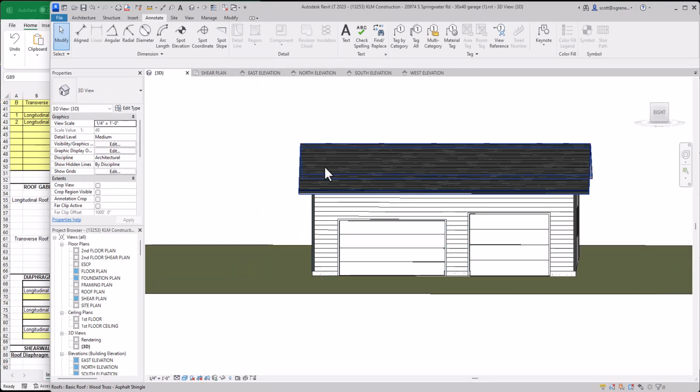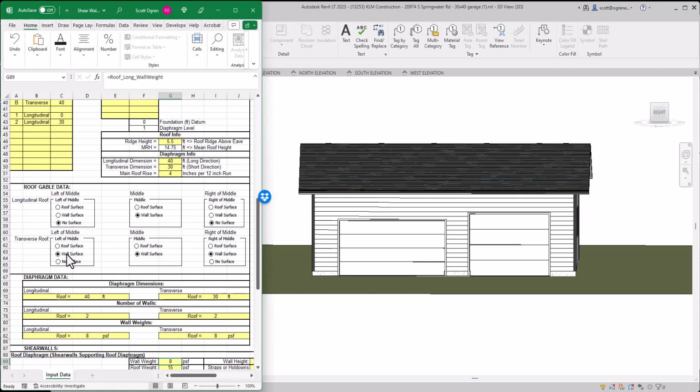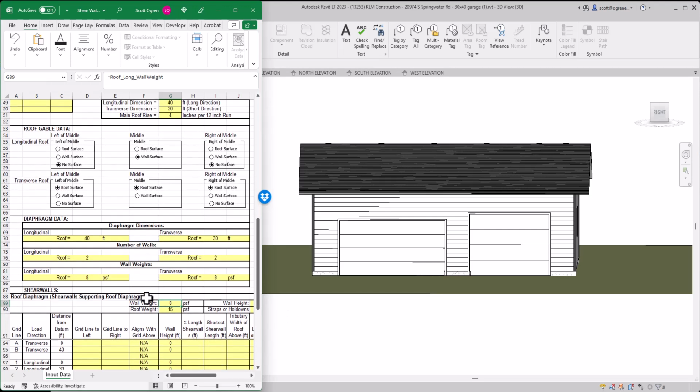And it's all roof. How you can estimate where the triangles are is to draw an imaginary line from eave to the center and back to the eave. So now we have the center triangle, the left triangle, and the right triangle. And all three of those triangles are roof surfaces. So now we're set. We come down here and we review.